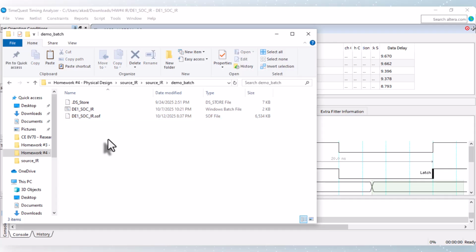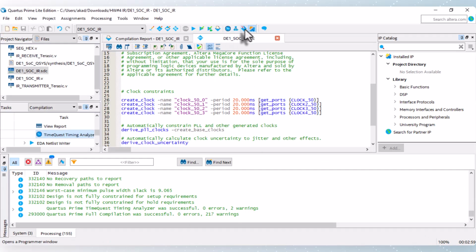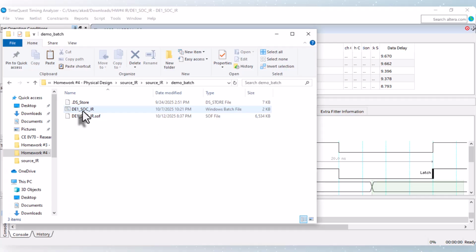I already turned it on and it's working right now. After that, I will run the FPGA board in a new way, not the exact way that we used to use with the programmer. This way is very easy and will let us run the FPGA board after we upload the SOF file, the stream file, to it.